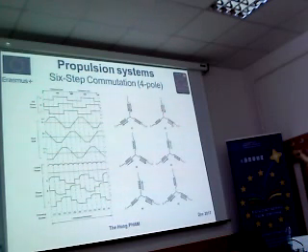So first A to C and A to B, and now from C to B, C to A, and the last is B to A and B to C. With these 6 cycles, the shaft will rotate one whole circle, 360 degrees.